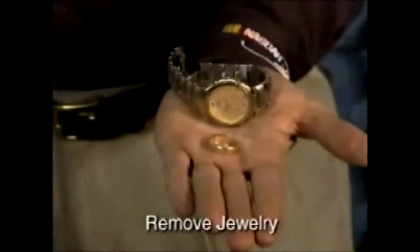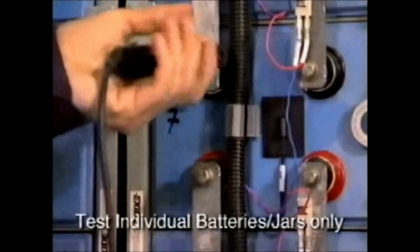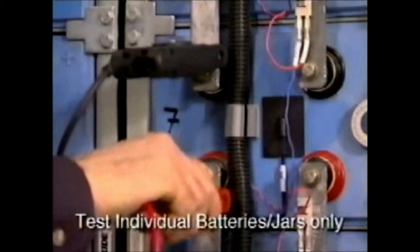Before conducting any tests, it's important to take safety precautions required by the facility or your organization. Be sure to protect your eyes. Remove all jewelry, including wristwatches. Also, never forget that analyzers are not designed to test entire strings at once. Test individual batteries or jars only.